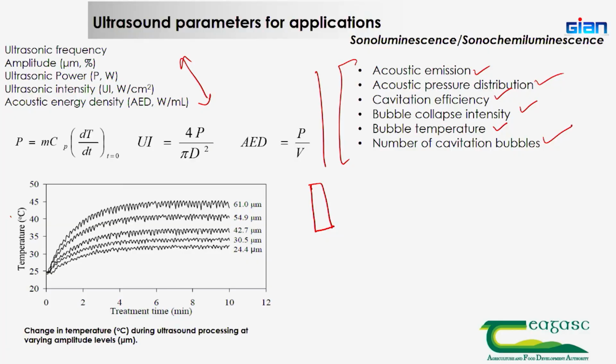So usage also depends upon the solvent, and you need to know the dielectric property of the liquid. Same for pulsed electric field: if there are particles it will cause a spark, and you cannot have air bubbles. I cannot cover all the technologies, but these are some of the limitations of each. So it has to be used based on understanding their proper working and mechanism. Then only should we think of applying.